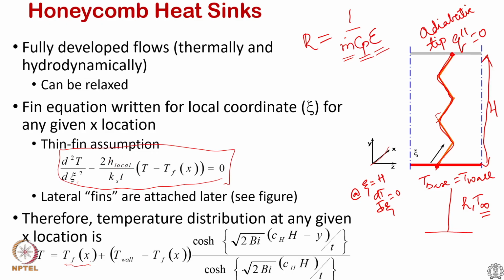in terms of Bo number, which is nothing but the local heat transfer coefficient times thickness divided by the wall thermal conductivity, the solid thermal conductivity. So, substituting and non-dimensionalizing, we get an expression. We keep this Ch as a constant. Ch will carry a value of 1 if there is no corrugation. Essentially, Ch acknowledges that there is some kind of corrugated wall that exists.